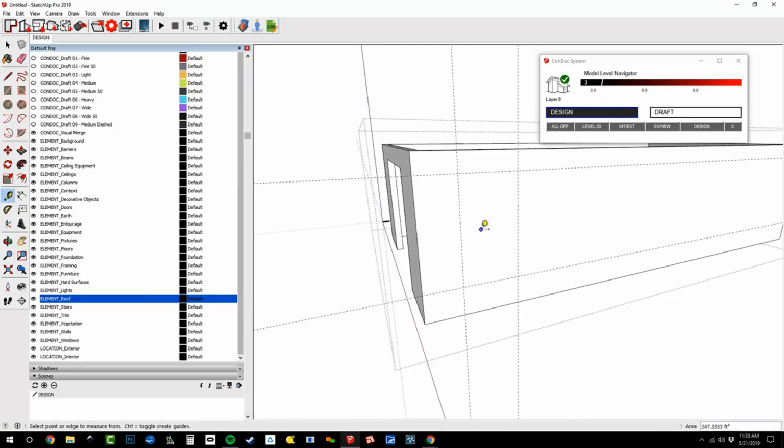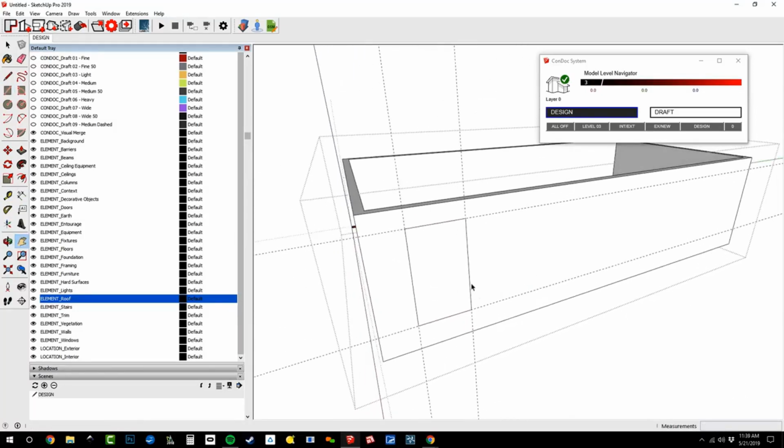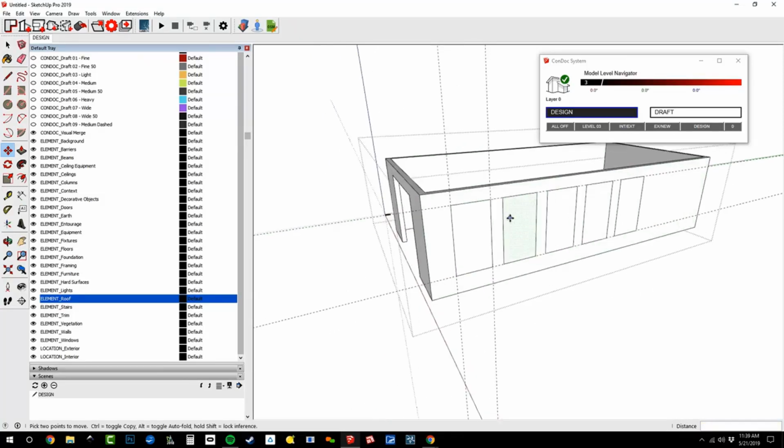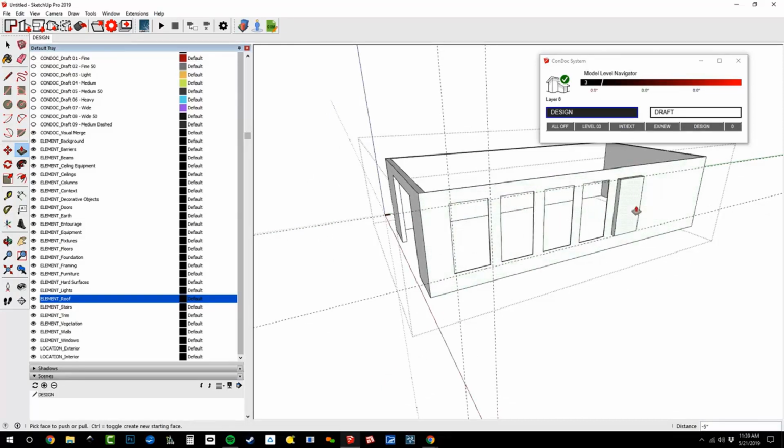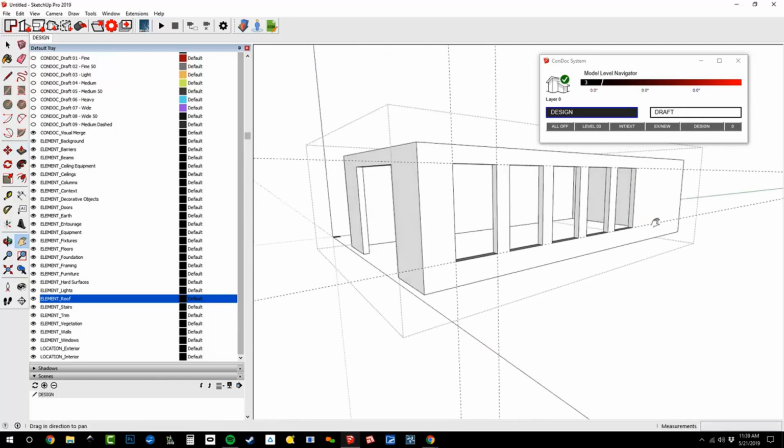That was like 7.6. Use my rectangle tool to snap to my origin point or my intersections, and then pre-select, use my move tool and make a copy of this at 4 feet, enter. And we want to do that 4 times. So 4x, enter. And we get 4 copies. I can now switch over to my push-pull tool and double click on each one of these, and that's gonna repeat the same push-pull. And I missed that last one, so I'll do that one manually.